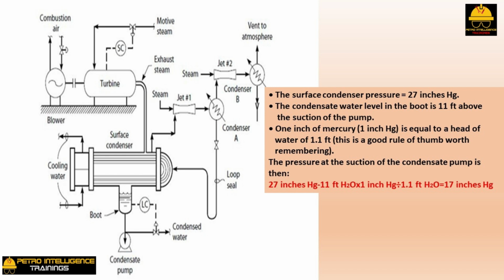Often, centrifugal pumps develop seal leaks. If the suction of a centrifugal pump is under a vacuum, air will be drawn into the pump through the leaking seal. The pump's capacity will be severely reduced. To stop the suspected air leak, he sprayed water from a hose over the pump's seal. Now, instead of sucking air, the leaking seal drew in cold water.